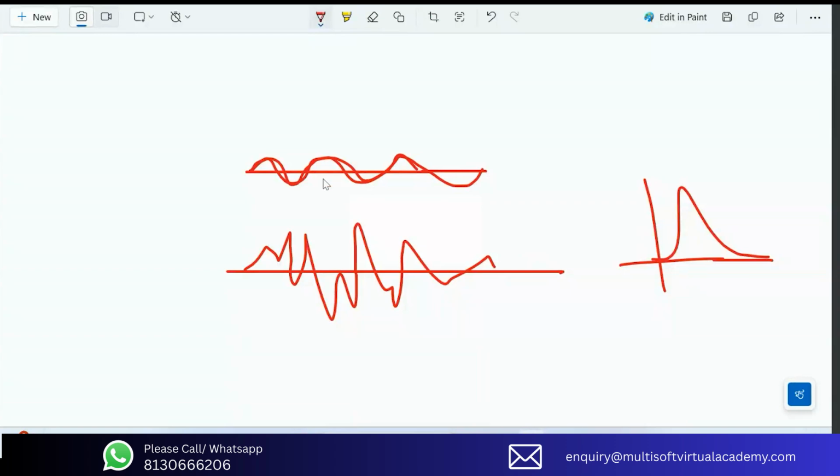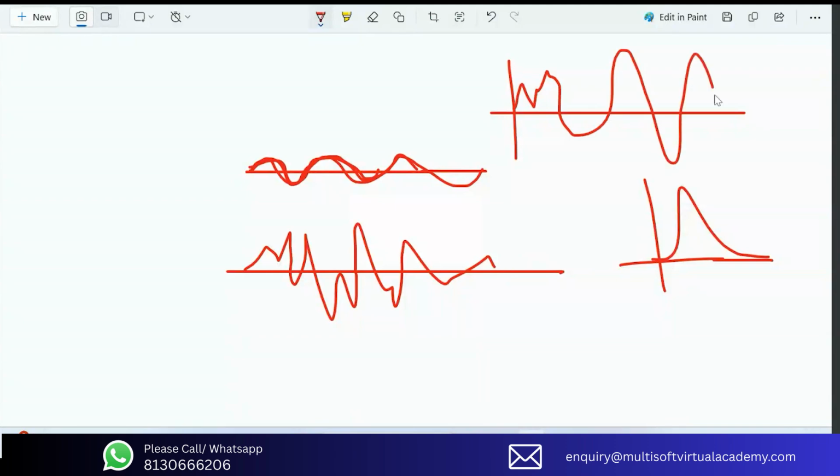Generally, if you run a riser dynamic analysis or a mooring analysis, once we apply an environment, there is a transition period where the system starts acting because of the forces, and then it will attain a steady state. For example, if we are looking at a tension response, when we start applying a wave, initially it could be a little random, but after some time it will become steady. As the waves are coming, it will move with the wave.